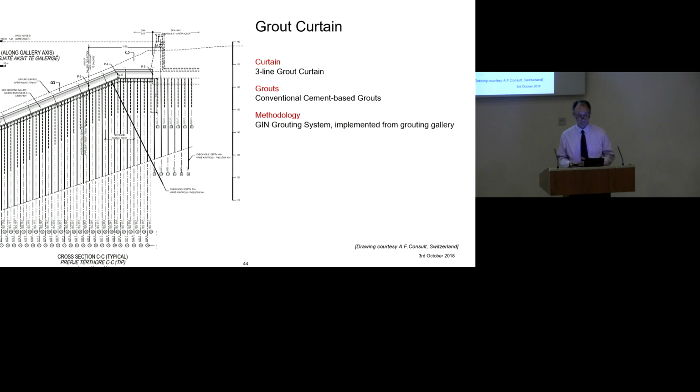So just putting a little bit of colour on there so you can see. So you can see the dam at the top in the reddish colour. The extent of the grout curtain is in the beigey colour. Interestingly, the planned extent of the grout curtain from the 1980s work was about half the height or half the depth of what was finally installed in the more recent construction. So we were being more cautious with the extensions of the grout curtain.